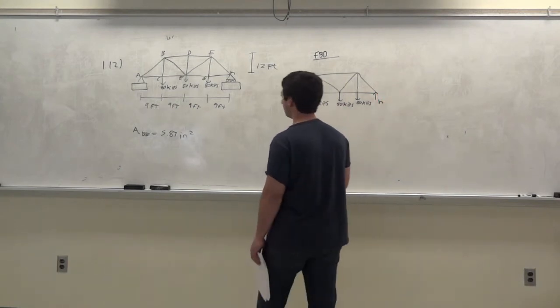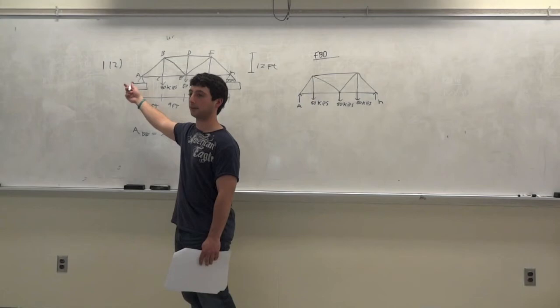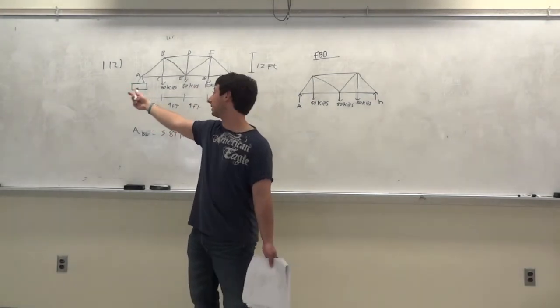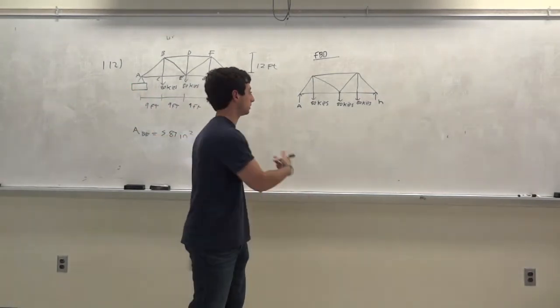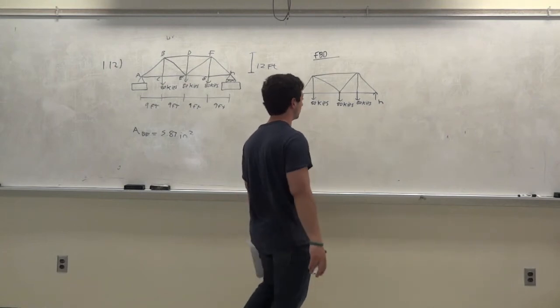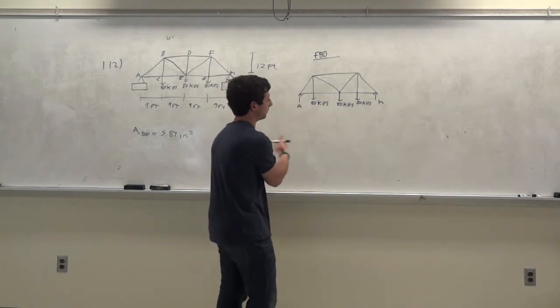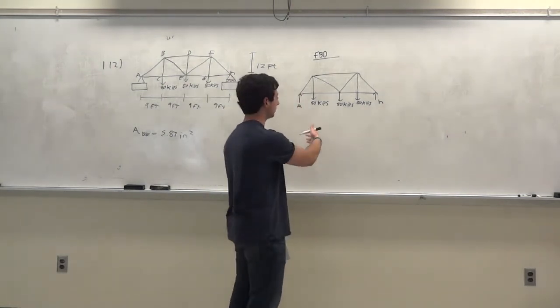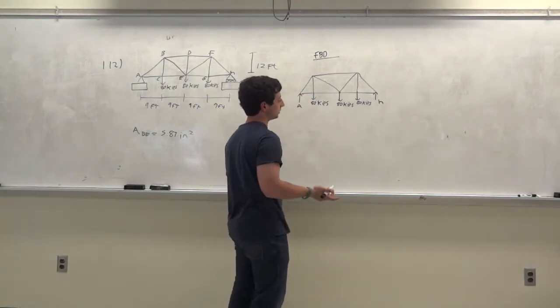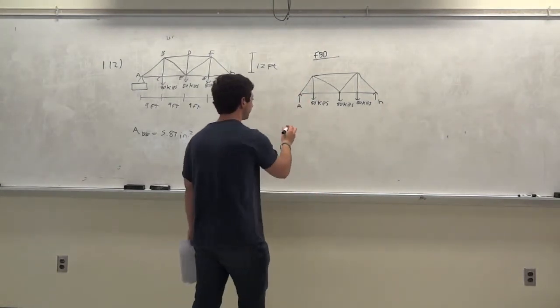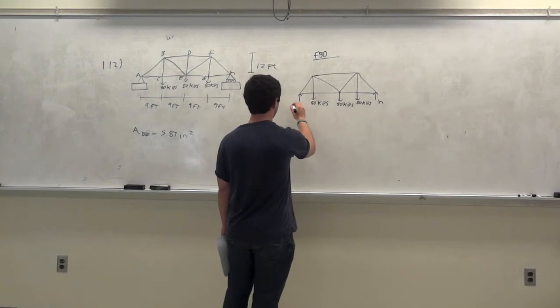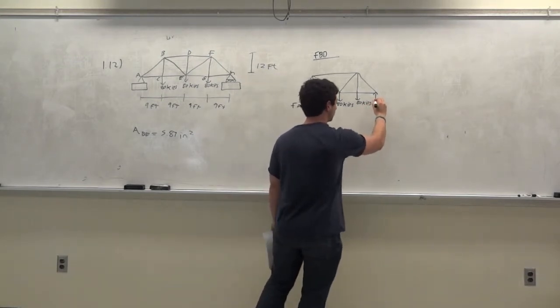Right? Normally you would have an AX, AY, right? But what does AX equal in this case? It's 0. There's no forces in the x direction. So don't even bother drawing it in, as long as you know that. If you don't feel comfortable just writing this, then put in AX, but it's just 0. So it doesn't matter. Okay, so let me just call this FA so people don't get confused.